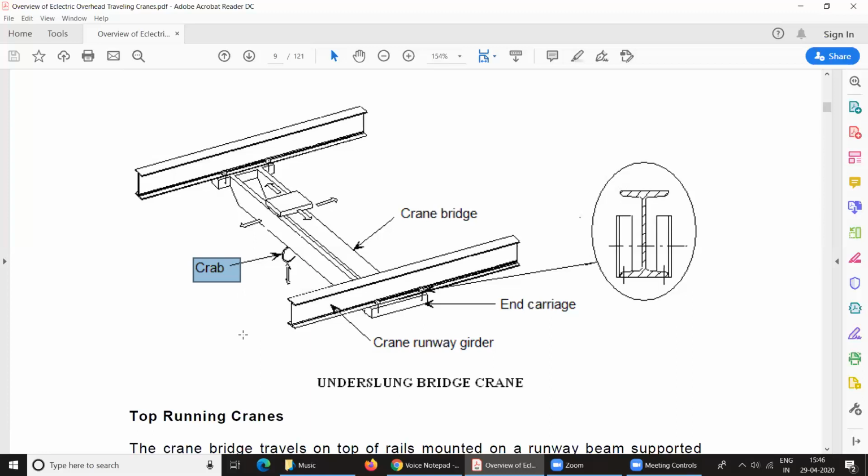A crane trolley is an independent machine consisting of the drum type hoisting equipment built on a framework, which is fitted with runner wheels driven by a motor through gearings. The hoisting motion is also motorized. The long travel of a bridge may also be manual through chain operation or motorized.